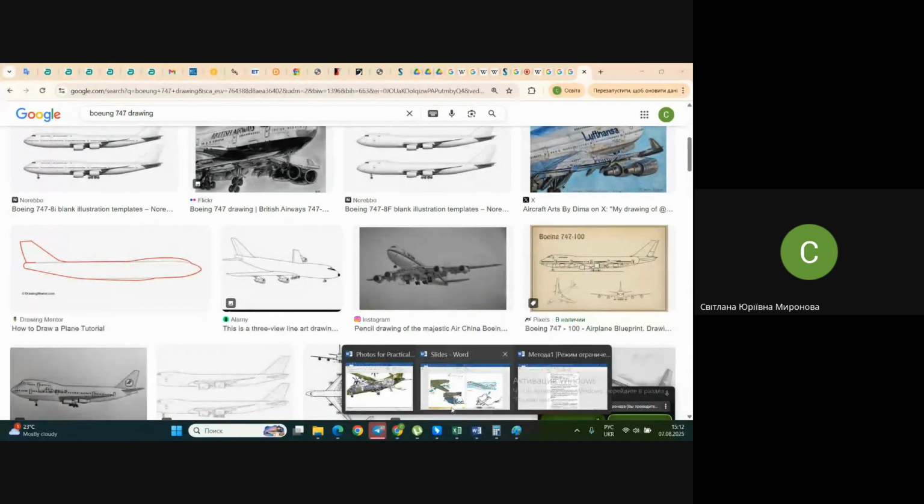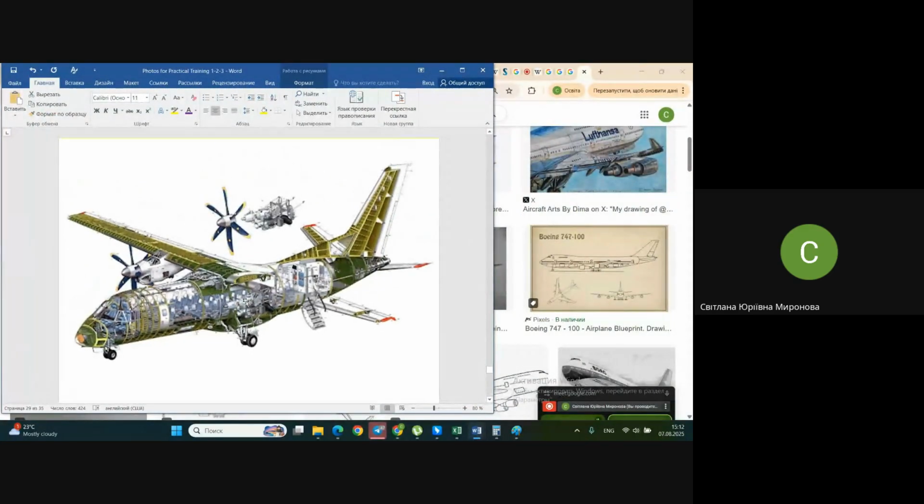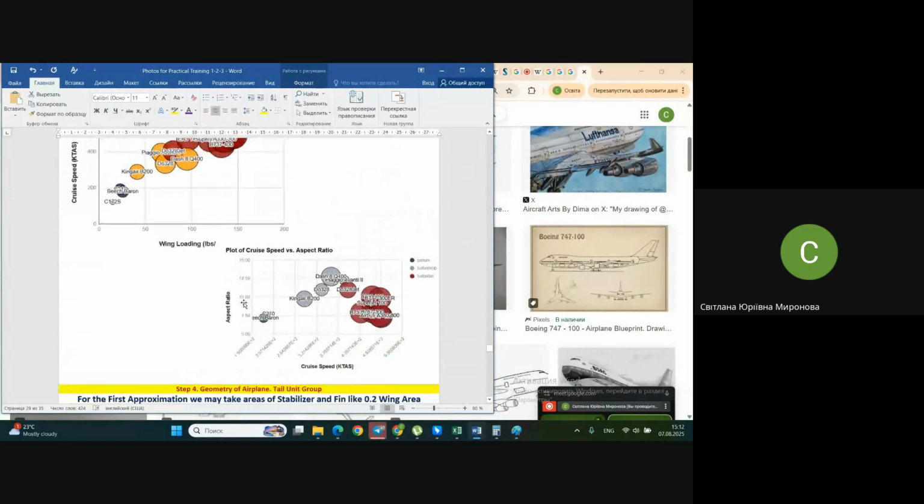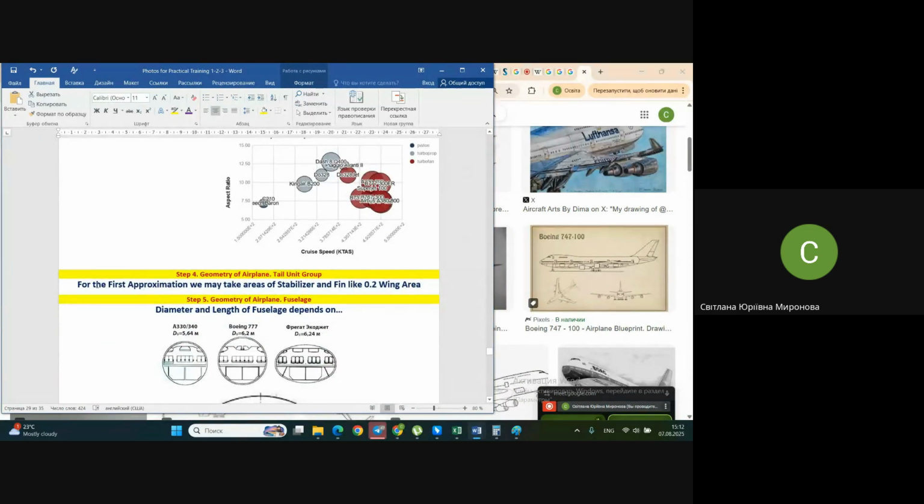So let's come back to the story about fuselage and composition of fuselage and wing with respect to each other. After the interruption we will continue. Right now what we need to remember is that after we know the area of the wing, how we know it, I reminded at the beginning, we need to calculate wing parameters. And for this, wing relative parameters help us. These wing relative parameters you may take either immediately from the internet if you find them for prototype airplanes, or you may calculate them on your own.